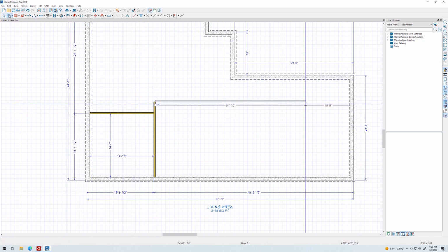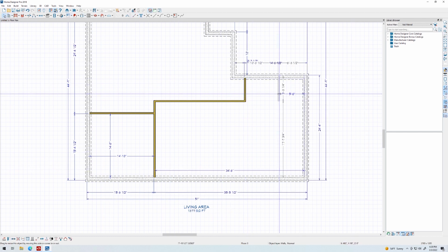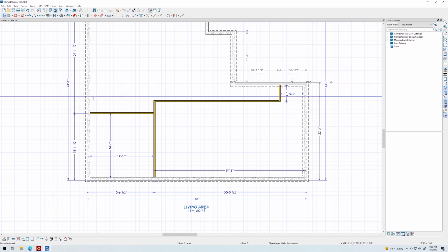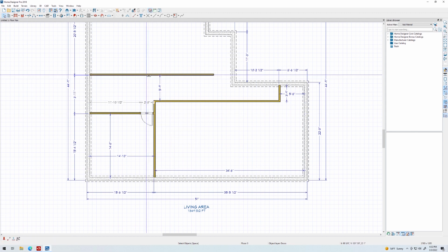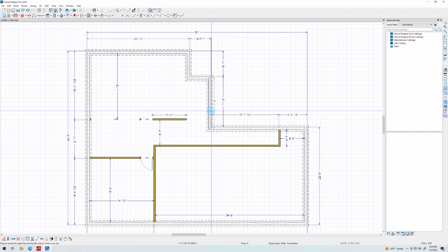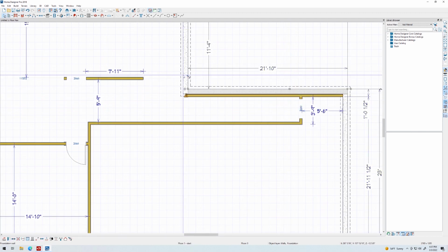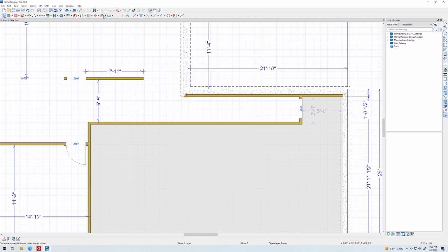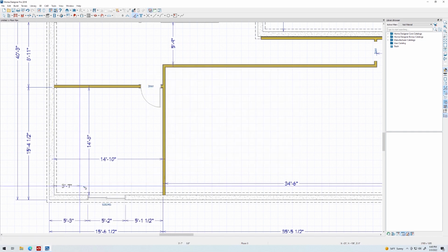Use the door tool to create doors and doorways. If you place a door that is the wrong size, you can right-click the object and go into its properties and enter the right size and style. Likewise with the windows. Right-click the object, go into its properties, and change everything according to what type of windows you have. Once you create a door type or a window size, you can copy and paste those objects into different locations into your drawing. Everything in your drawing is adjustable.